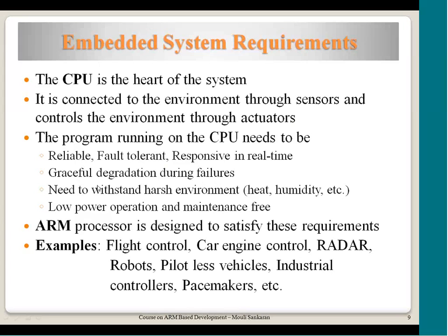Whenever you see embedded systems, they say that even if it fails, there should be a graceful degradation. Even if the access card reader for the office has failed, it should fail in such a way that it keeps things safe. If it is a locker room, maybe it should keep the door locked, where very confidential documents are kept. Or if it is an office, maybe if there is an emergency, people should be able to come out.